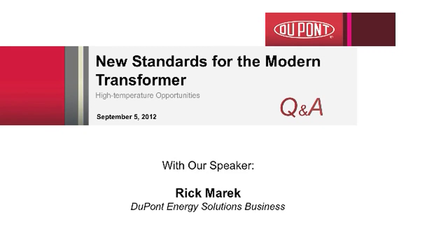Thanks, Rick. How does dielectric strength of Nomex compare to conventional materials in a liquid-filled environment? Well, we find that the Nomex insulation has approximately the same dielectric strength as conventional kraft papers, both in the board and in the paper materials.